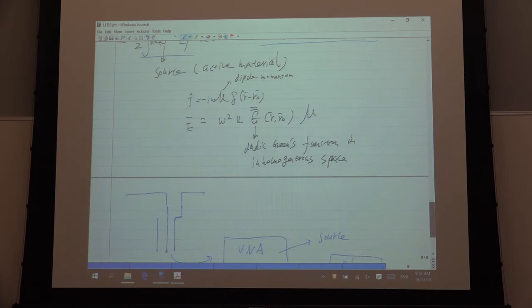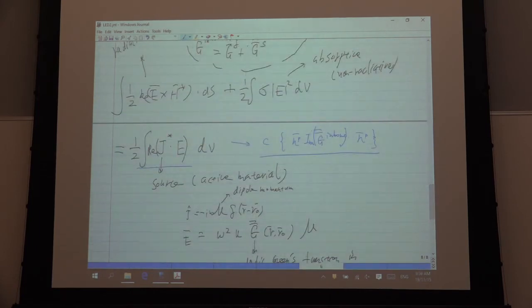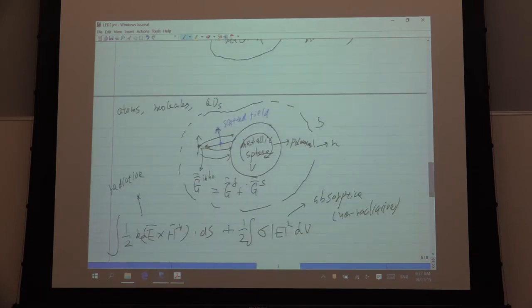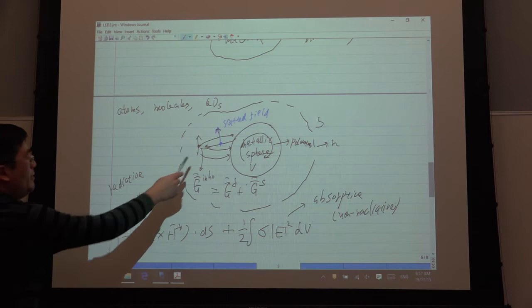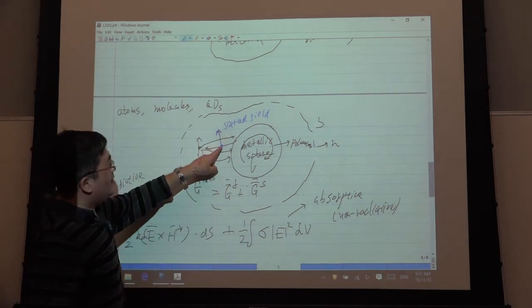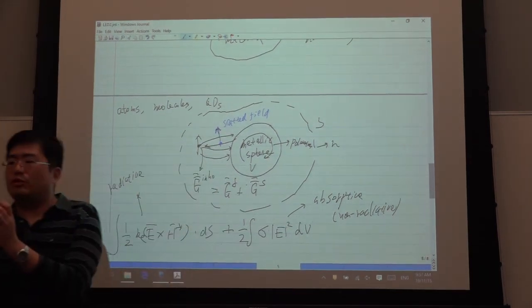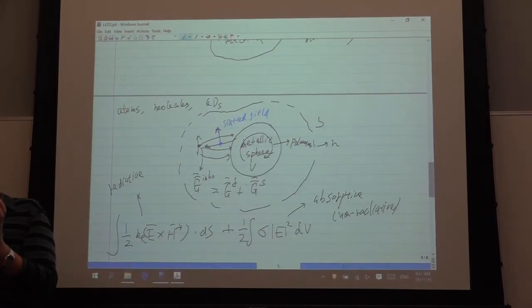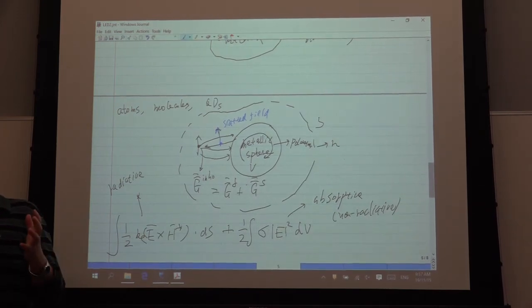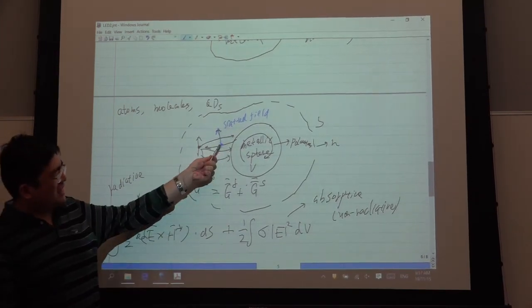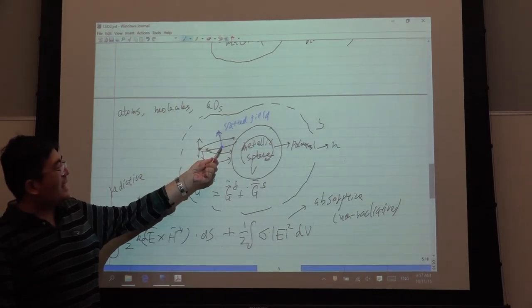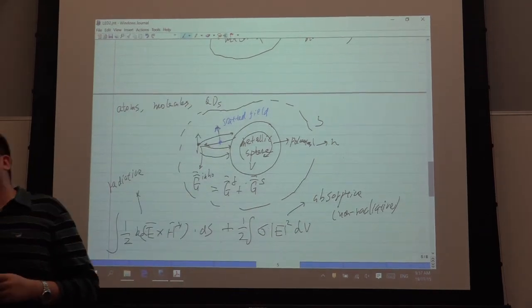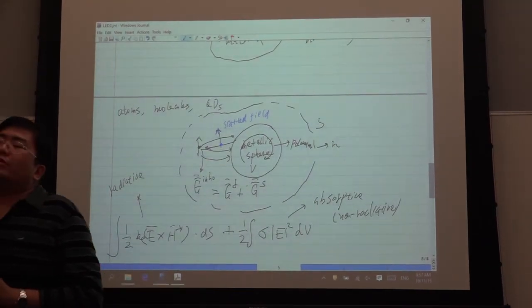So from this equation, I said this Hertzian dipole point is a quantum dot, atom or molecule. You increase the E field here, you just increase absorption of this material. Then they can emit more power because absorption and emission are balanced in the spontaneous regime. So you just enhance the E field at this point, you enhance absorption of this active material, then they can emit more power. So there's no contradiction. It's quite different from the traditional way.